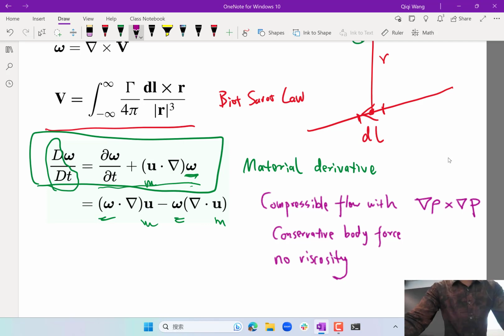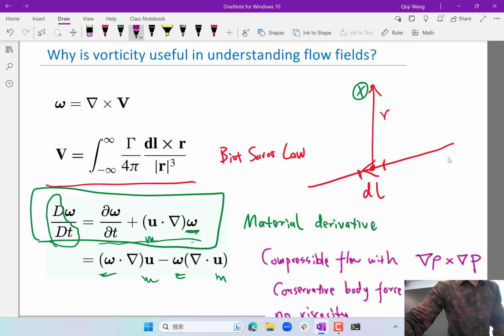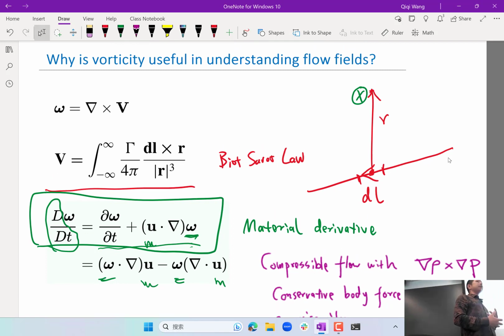So in this class we looked at what vorticity is and in what scenarios a flow field has vorticity, and looked at a mental model of a concentrated vortex. On Wednesday we're going to look at specific examples of the flow field induced by just the trailing vortices from airplanes.